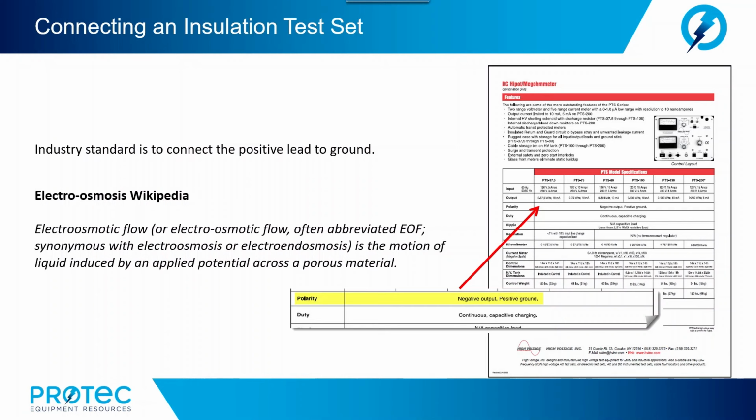Now, since insulation testing is typically concerned with safety, maintenance, and/or troubleshooting, the worst case reading would be the one which yields the most relevant information. Also, negative polarity is preferred since water molecules are positive polarity and are attracted to the negative voltage, which gives a more comprehensive picture of insulation condition.